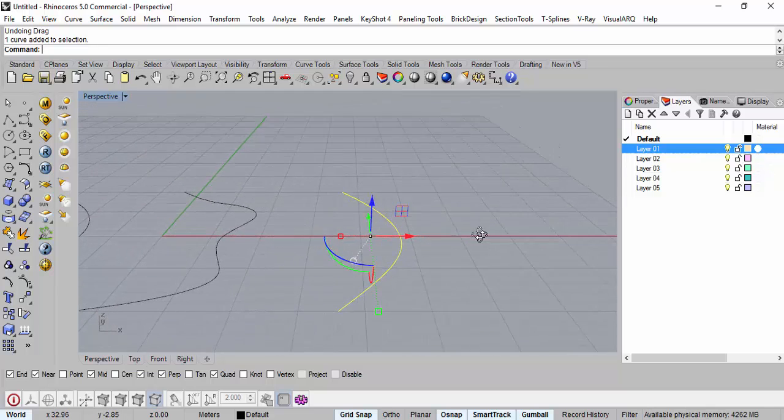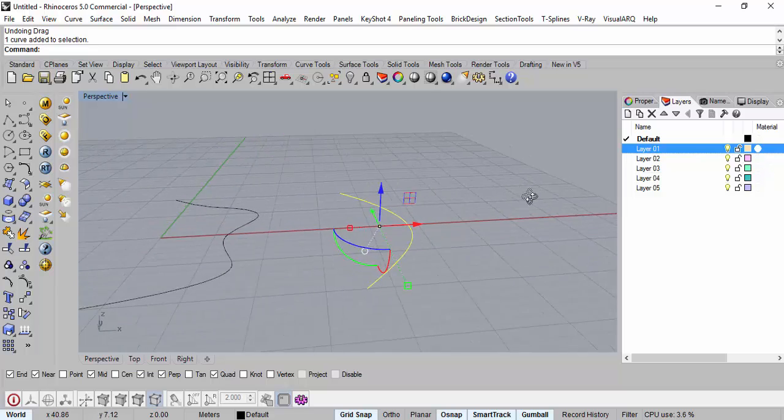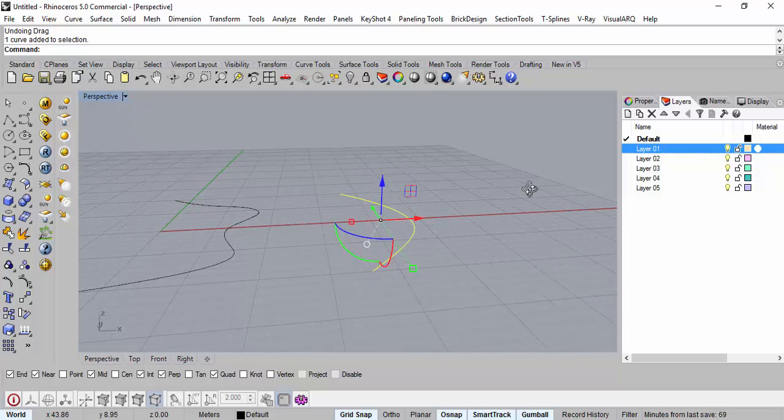Now about which axis do you want to rotate it so that it becomes vertical? Green? Not green? So this is the green axis. We want to pivot it along that, right? So you can just double click on this.